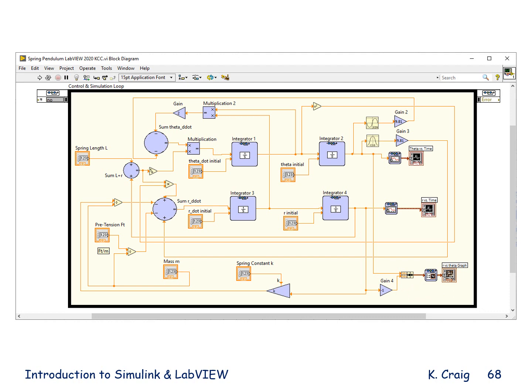And what this plot gives me, as it did in the Simulink diagram, is what I would see if I attached a laser light, a laser pointer, to the spring pendulum mass as it went through its motion. Its simple pendulum motion and its spring mass motion, and its transference from one mode of motion to another. So this then is my complete block diagram.